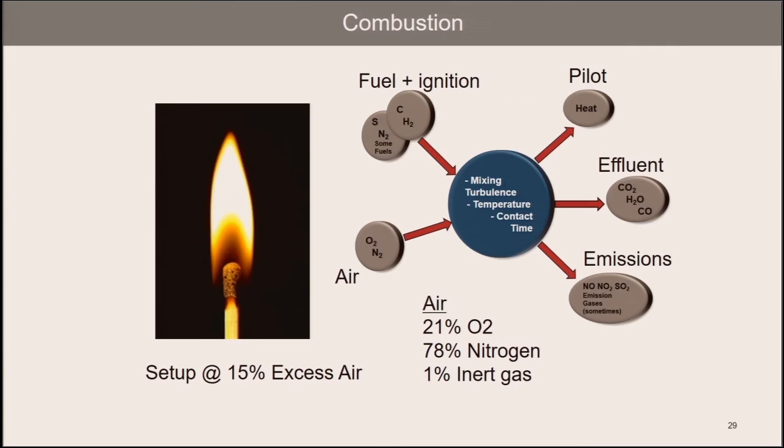Remember, when speaking about too much excess air, that combustion only requires oxygen, and air contains about 21% of it, but also about 78% nitrogen, which does nothing for combustion, but it only robs BTUs from the burner and sends them through the stack and out to the atmosphere.